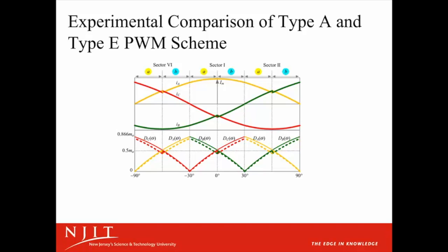Furthermore, the curve of the effective duty cycle will contain step changes which occur in 6-degree intervals. Because the phase current is determined by the effective duty cycle, the phase current will also be distorted and will contain low frequency harmonics that will affect the THD. The maximum loss of duty cycle is obtained when the magnitude of the primary voltage is minimum, theta equals 0. As a result, the effective modulation index MA should be within the range of 0 and DSX max.